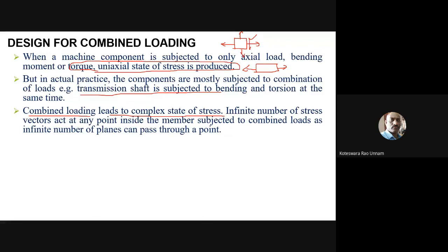Even if I have shear stress, shown something like this, I'll call it a biaxial state of stress. This is plane stress, or biaxial. You studied plane stress analysis, so you might have done all these things. To represent the triaxial state, meaning stress in three directions, you need to take a cubic element, not simply a square, and represent all the stresses acting on this cubical element.